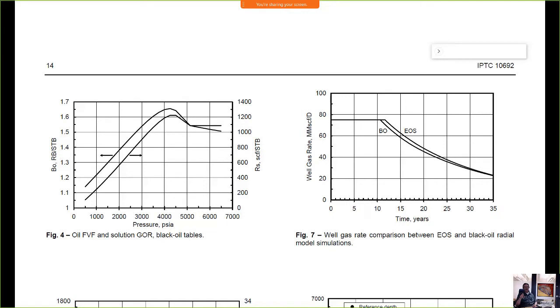And you'll get this non-monotonic behavior like this because the oil that drops out right at the dew point, if you took and flashed that oil, that incipient oil, to the surface, you get a 38 API or maybe a 32 API. But then as you go further down, the condensate that you're dropping out is becoming lighter.